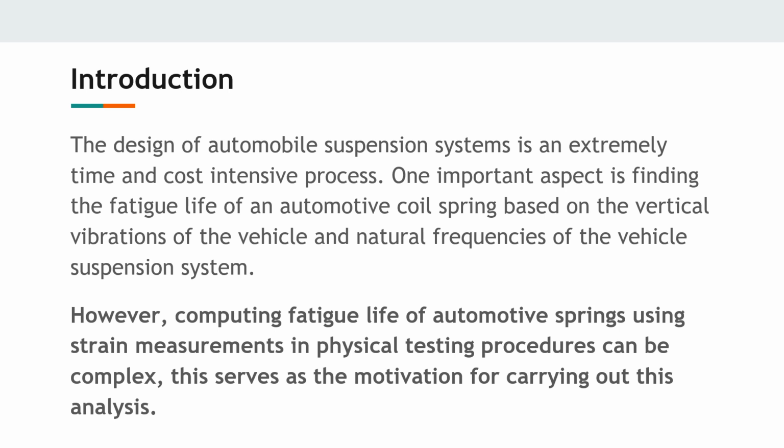The design of automobile suspension systems is an extremely time and cost-intensive process. One important aspect is finding the fatigue life of an automotive coil spring based on the vertical vibrations of the vehicle and natural frequencies of the vehicle's suspension system. However, computing fatigue life of automotive springs using strain measurements in physical testing procedures can be complex. This served as the motivation for carrying out this analysis.